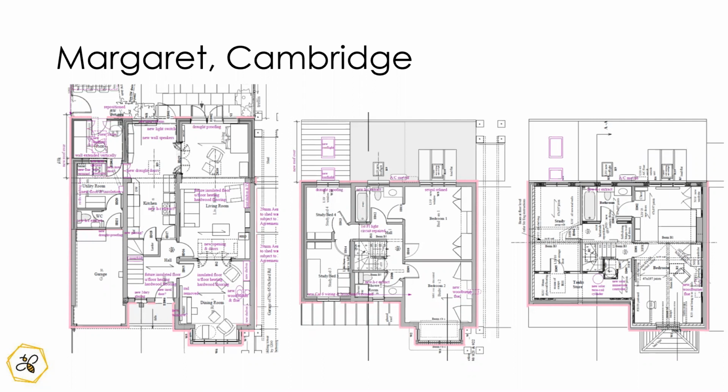I mean, Daikin only runs about 10 or 12 meters between the outdoor unit and the cylinder. Only 12, because I've understood about 30. Yeah, it all depends. I thought I would come across the front garden, go up within the EWI, external wall insulation, and then just go straight in the loft floor to the tank, to the hot water. It's not recommended. But it's tall. It's way up there. So I was thinking of maybe. Sorry, what's not recommended? To have a long run between the heat pump and the cylinder. Yeah. Okay. I was thinking more.